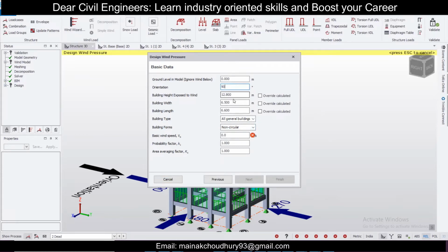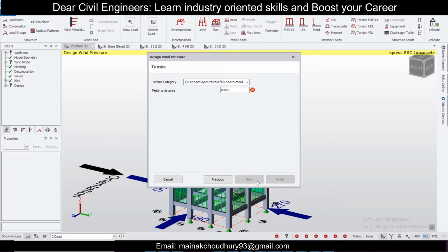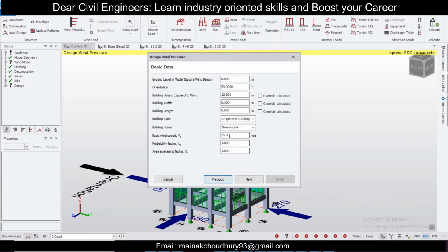Building height exposed to wind, the maximum height it automatically takes, and then the basic wind speed is 55 for Tripura, and I have already shown in the video on the wind of the IS code 875 part 3. You will find a table and also a map in which the basic wind speed is located, and the K1 and K2 factors will be 1 here for Tripura. And again, the detailed part, why this one, you can find in the video on the tips part. So it is the same thing. I'm not going to repeat this, but basically you can just go through IS 875 part 3 for those factors.